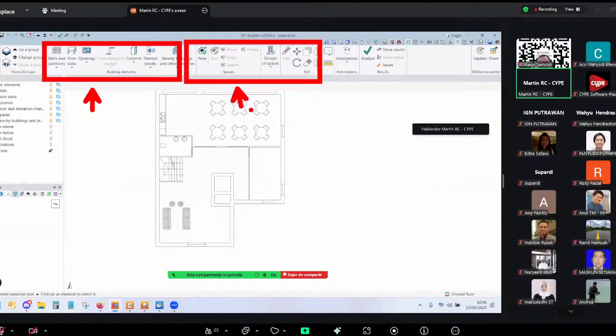That's easy. We just need to define them and put a name to them and so on. And once we've done that, we hit the analysis tool so that the edges and adjacencies information, thermal breaks or not, facades or internal partitions, all that information is generated automatically, right?